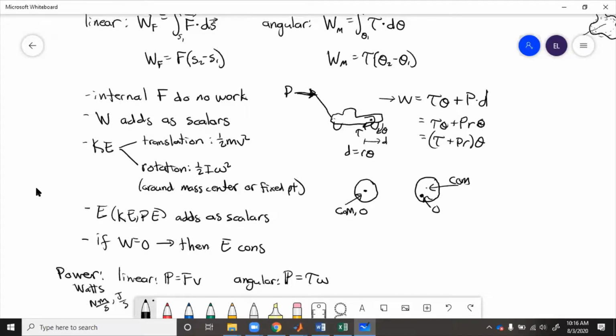So the interesting thing here, we can translate it into the gears things. Say we had omega 1, omega 2, R2, R1. One of the reasons that people will use a gear train is because they want to use a little motor to turn a big load.